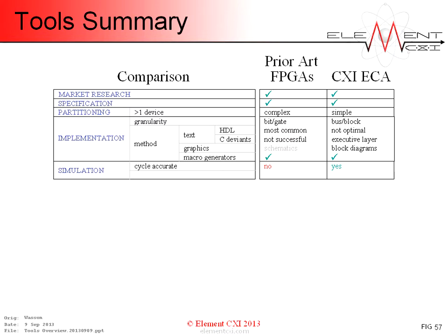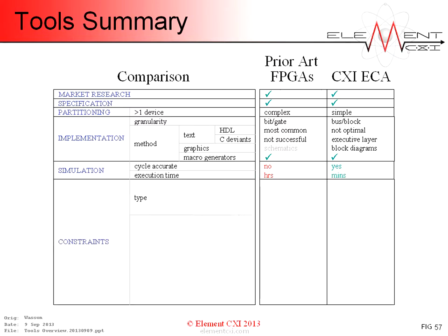For similar reasons, gate and LUT simulation time for FPGAs can run for hours, but for ECAs is mere minutes. Constraint types for FPGAs primarily control partitioning, placement, and timing, the latter meaning individual net timing. For the ECA, partitioning and placement constraints are very applicable, but net timing constraints are entirely unnecessary.